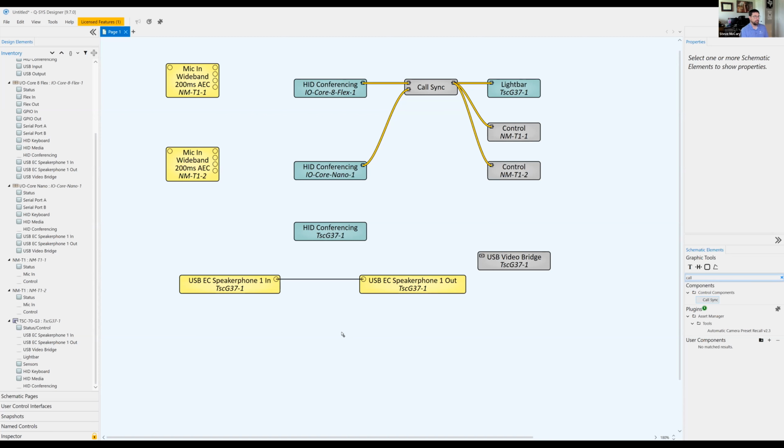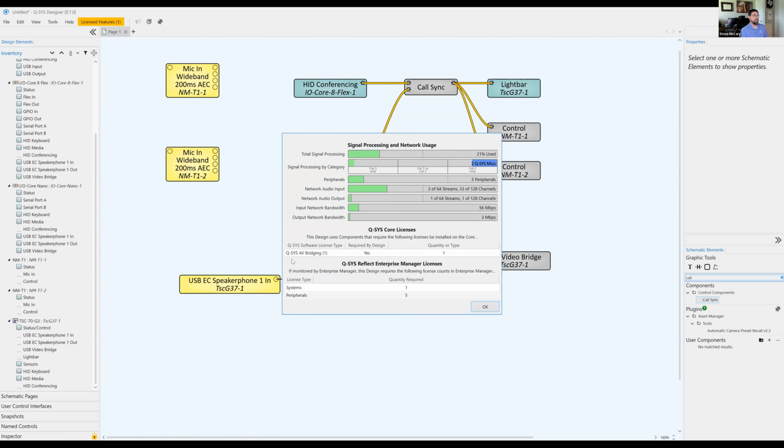And the other thing to remember is that the AV bridging license is only applied per device. So if you have 3 touch panels in 3 different rooms, all on the same system that you all want to use the bridging out of, you would need 3 AV bridging licenses. That is applied on the core, but it is then per device that you use as a bridge.